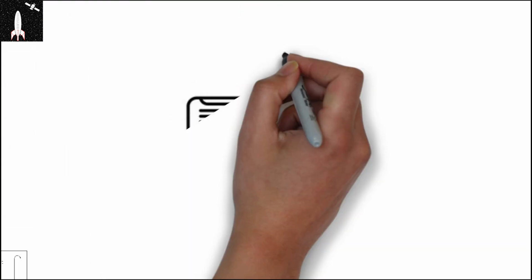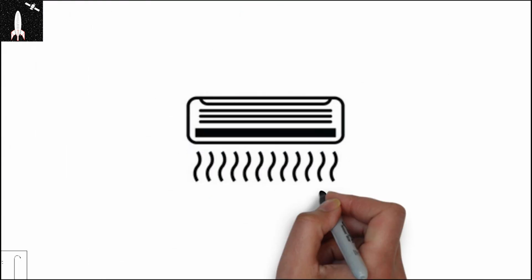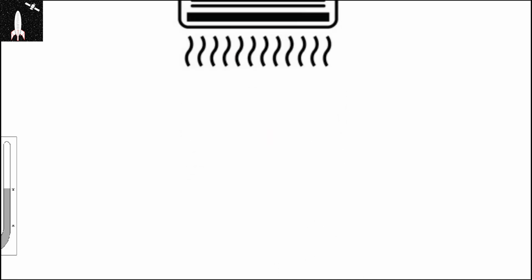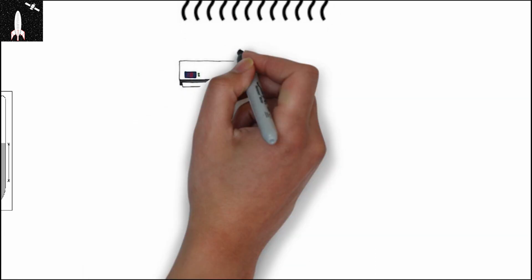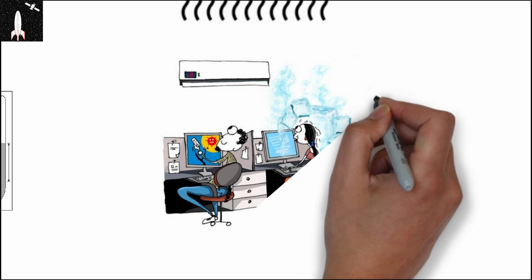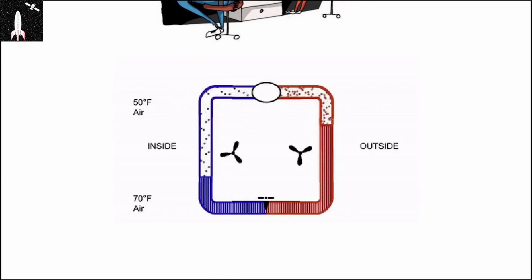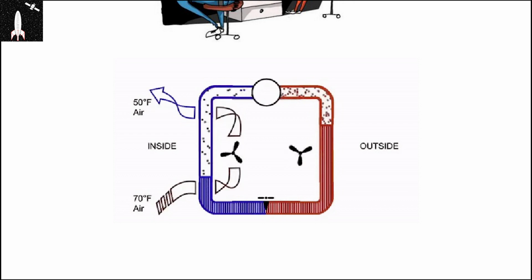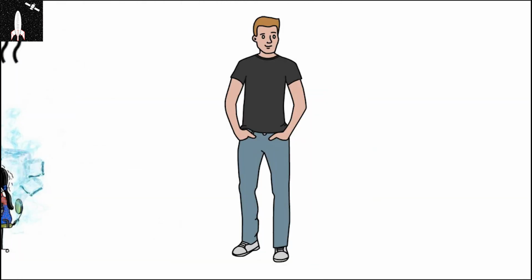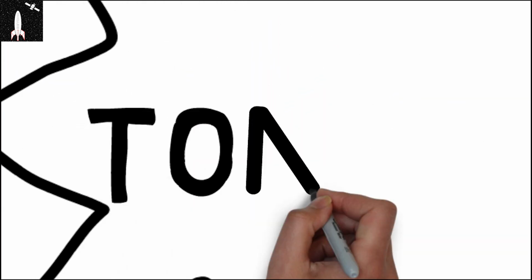This low temperature refrigerant should be at a temperature lower than the room's temperature. Now when it is passed to the evaporator, the temperature of the room drops. The refrigerant gets converted into vapor during this heat absorption at the evaporator. This is how our AC works. So is the video over? Not yet. Now we will see what ton means in our AC.